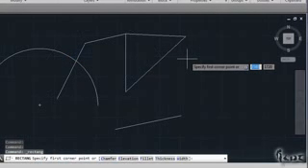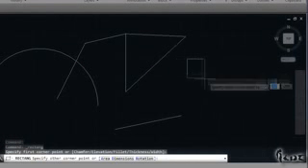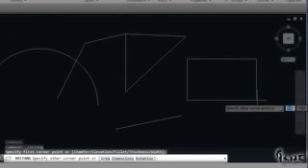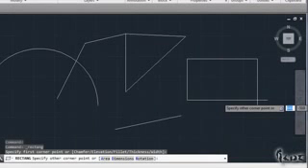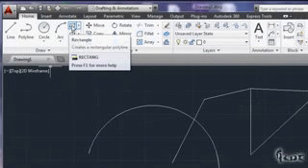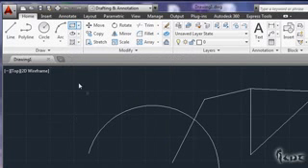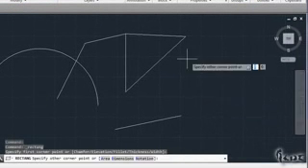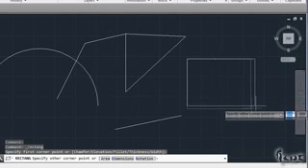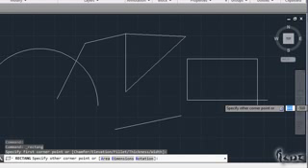While drawing, the command line below will guide you through. Each time you draw or do anything, the command line will tell you what to do or any choices, which are indicated through brackets. Choose Rectangle. After you set the first point, you can put a precise area or rotation. If you want to rotate your shape, just type R in the white slot next to your pointer.